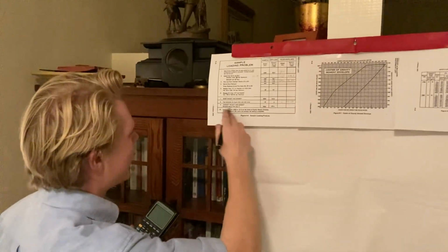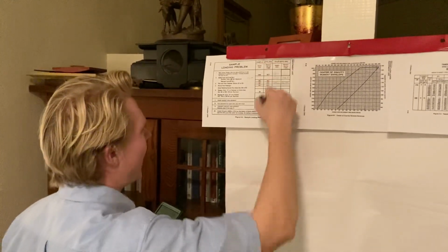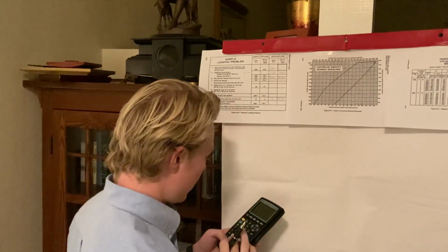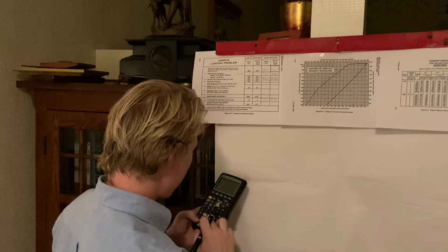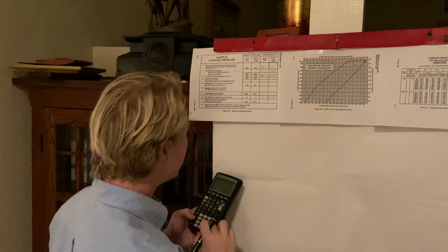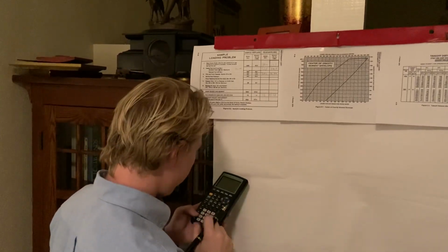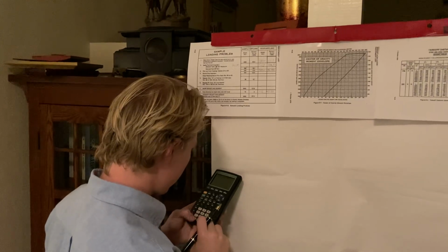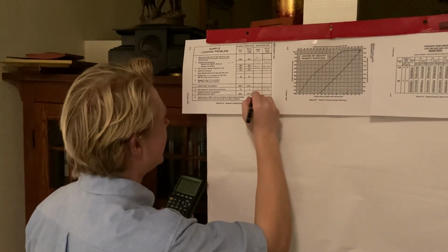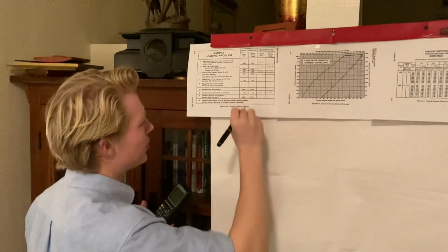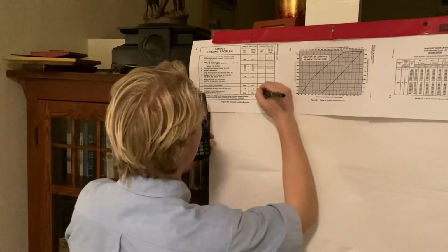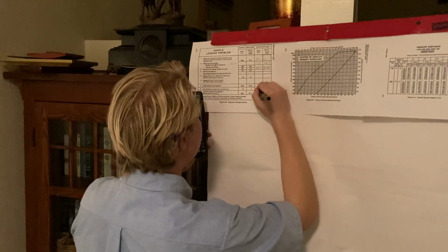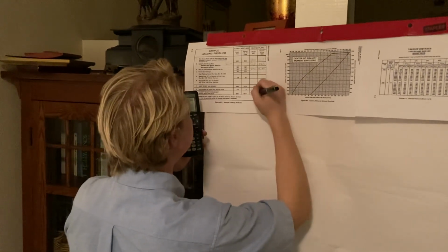So to get the takeoff weight and moment, we're gonna add these columns up. So we're gonna get 1,800 plus 528 plus 340. And then we're gonna subtract our 6 pounds of fuel. And that gives us a total weight of 2,662.